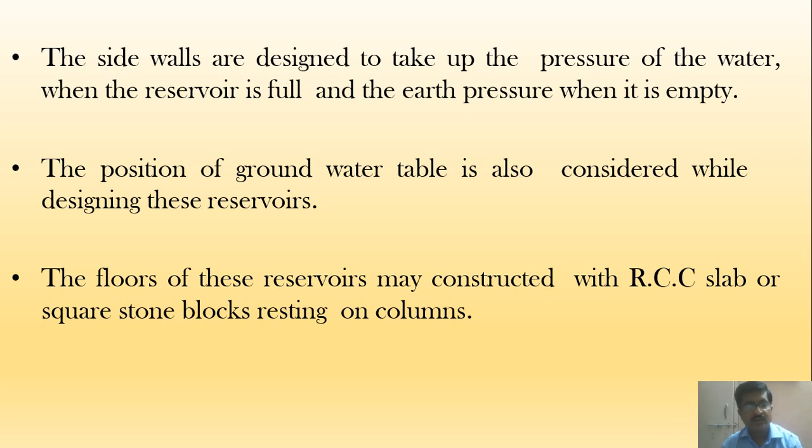Okay, in that case, the walls of this reservoir may be acting as a retaining wall, isn't it? So we have to plan or design accordingly. The position of the groundwater table is also considered while designing these reservoirs. If you are providing underground reservoirs, we will also see the groundwater table where it is available.